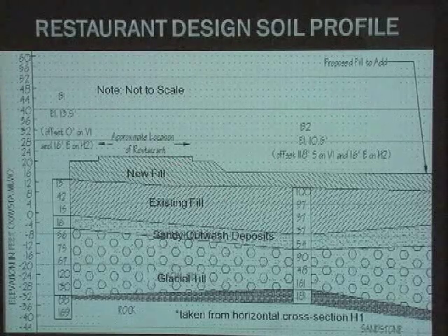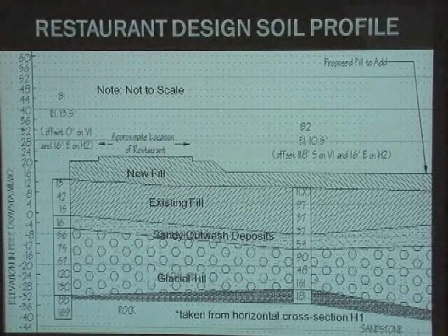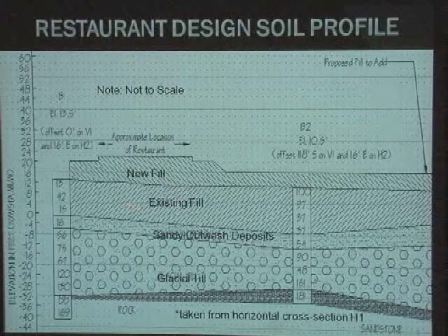For our foundation, we will be compacting the fill beneath it through scarification in the beginning because the soil is very varying. So we're going to scarify it, compact it, bring in new fill in lifts, and put the foundation for our restaurant right on top. Eric's going to go into the rest of the site.